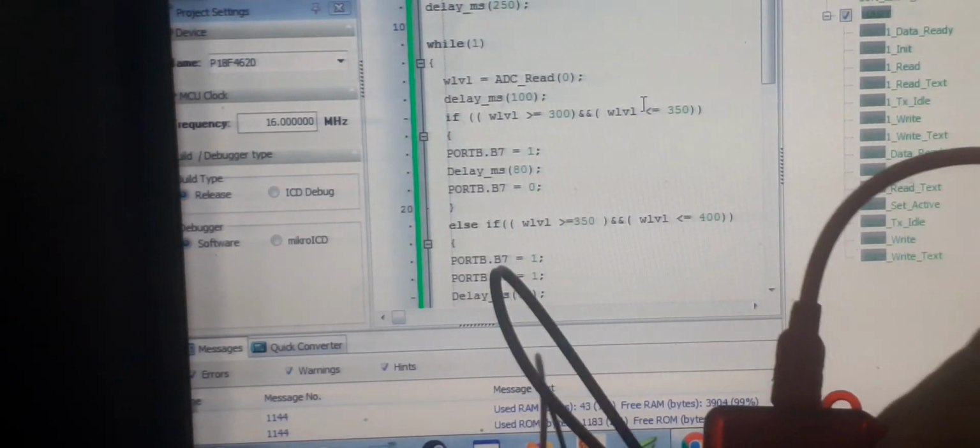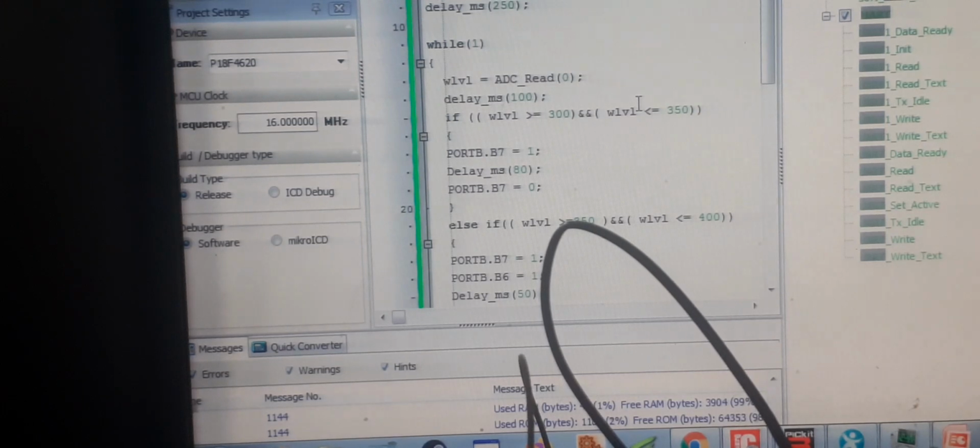Let's check it. Disconnect this PICkit, connect power from the device. Alright, you must be able to see everything, the whole setup, the LEDs, the glass, and the controller as well. Alright, here we go. Let's get started. Open the tools, UART terminal, select COM4, connect. Now power up the PIC, so readings start coming. Alright, the device is powered up, so we are getting our readings. It's like this, no LED blinking.